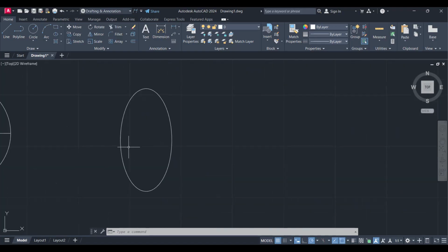Which values can you take here? You can create this this way. And then for this part, we have another way, which is by center point. If you have the end point, then you can create by the end point. If you have the center point, then you can create by use of the center point. How can we create by the center point? Just C, enter, and then specify the center point first. This is your center point, right?